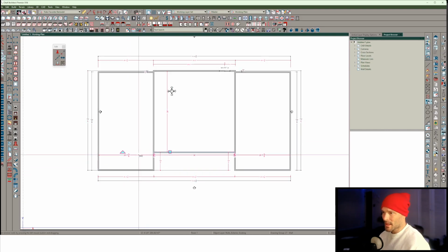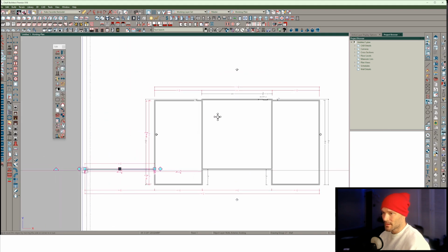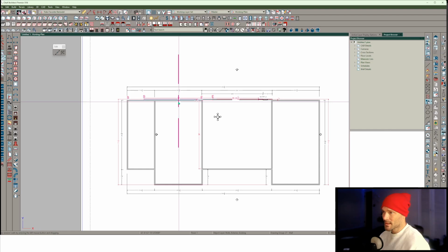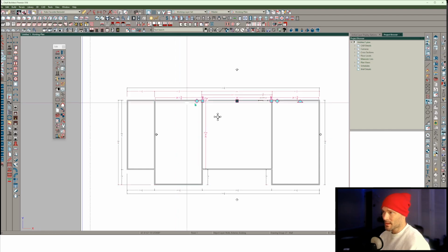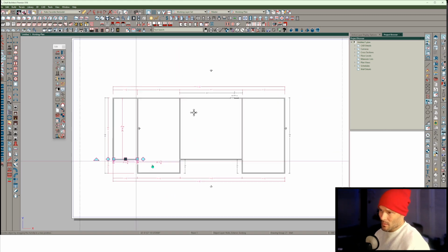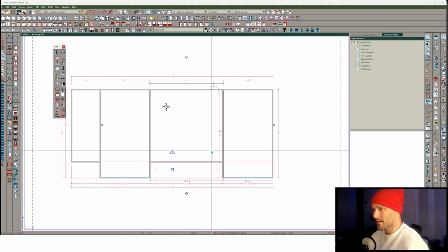And then the other thing that's happening here is we've got another wall, kind of like this front wall. Now that makes a new wall that's aligned, and we've got an extension of the house that carries through like this. And then we could use the connect walls to just join that to this back wall. And let's just use the centering tool to center up this back wall along that whole projection. There we go. Now I want to select a couple of these walls and make them gable end walls in this case. And I'm not even going to worry about the back of this house.